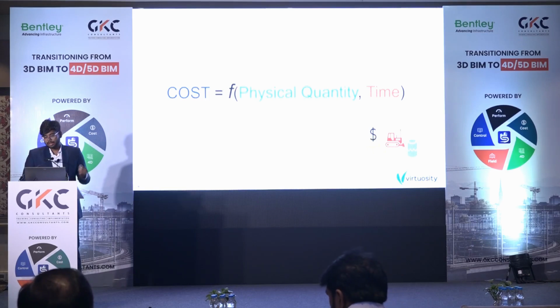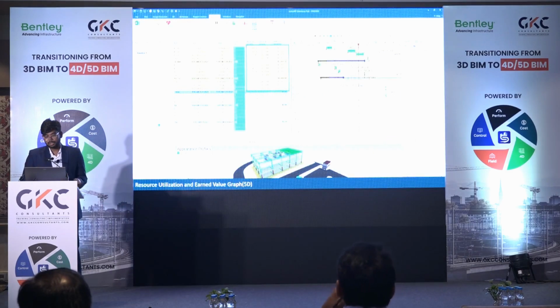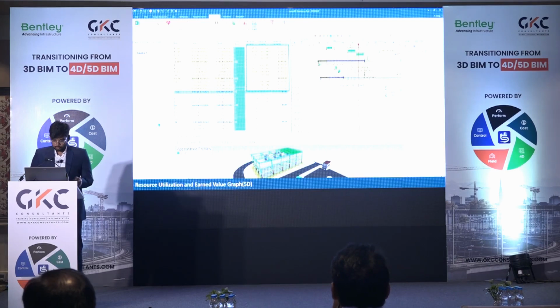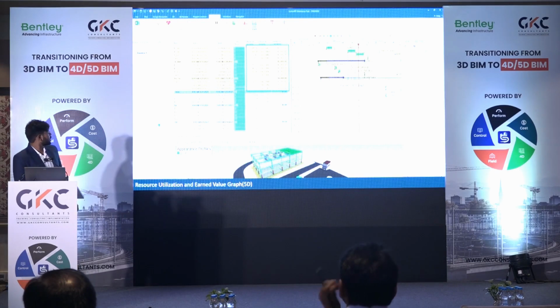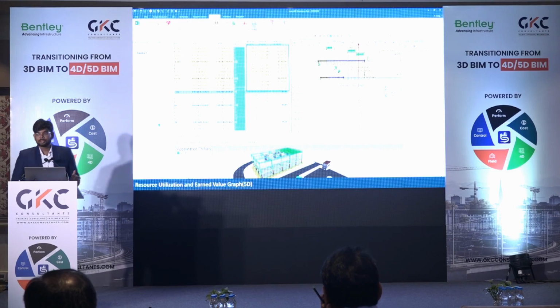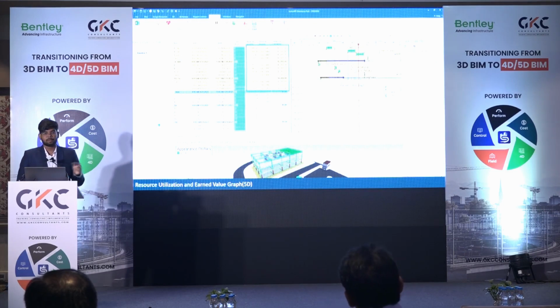So let's say that at this point in Synchro, what information do we have? We have the schedule, and the schedule is linked with the 3D resources. So what's the advantage of that? From that point, we start accumulating the physical quantity of the 3D resources which are assigned. So let's say that there are 3 activities for the piles, and for each activity we are constructing 50 piles.